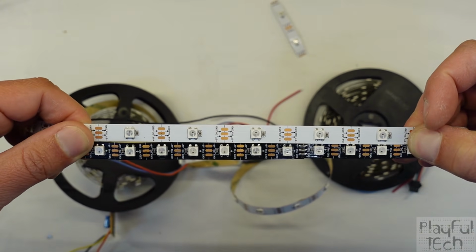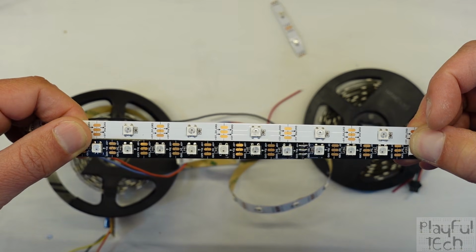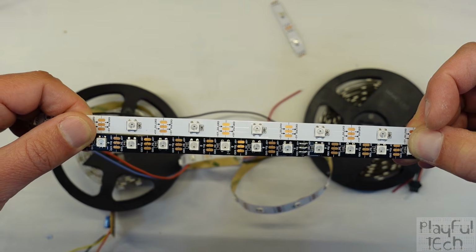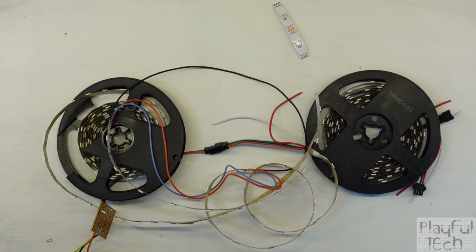Now both strips work in exactly the same way, but having a higher concentration of LEDs will make the strip brighter and more uniformly distributed, although it will also mean it will draw more current as well. So that's when you might need to use that additional secondary power supply I showed you with the 5V and ground connections, rather than trying to power the strip directly from the Arduino.